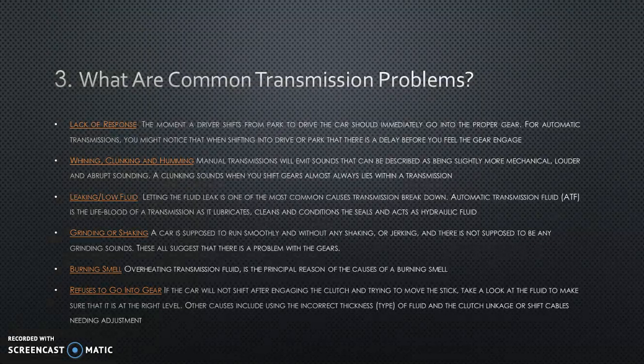Grinding or shaking. A car is supposed to run smoothly without any shaking or jerking, and there is not supposed to be any grinding sounds. This all suggests that there is a problem with the gears. Burning smell. Overheating transmission fluid is the principal cause of a burning smell.